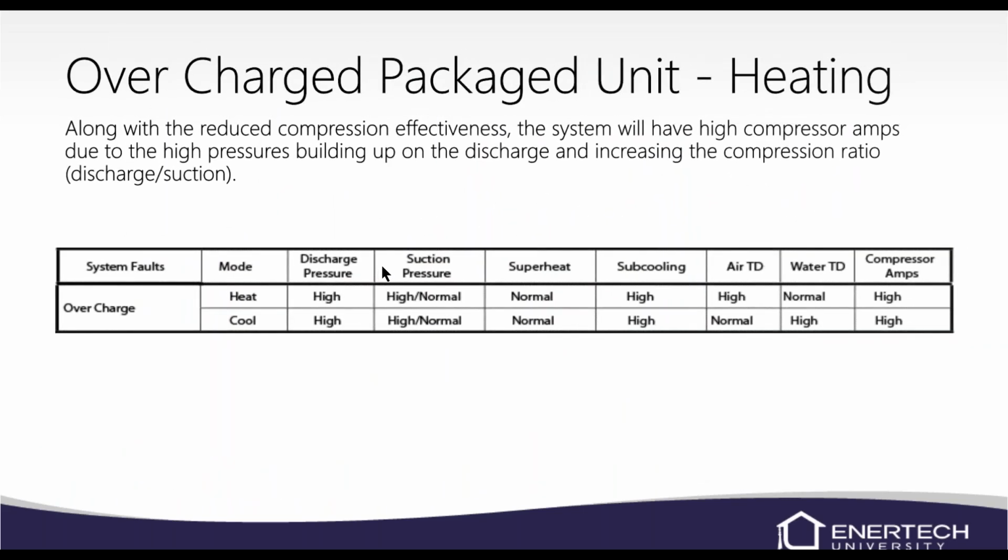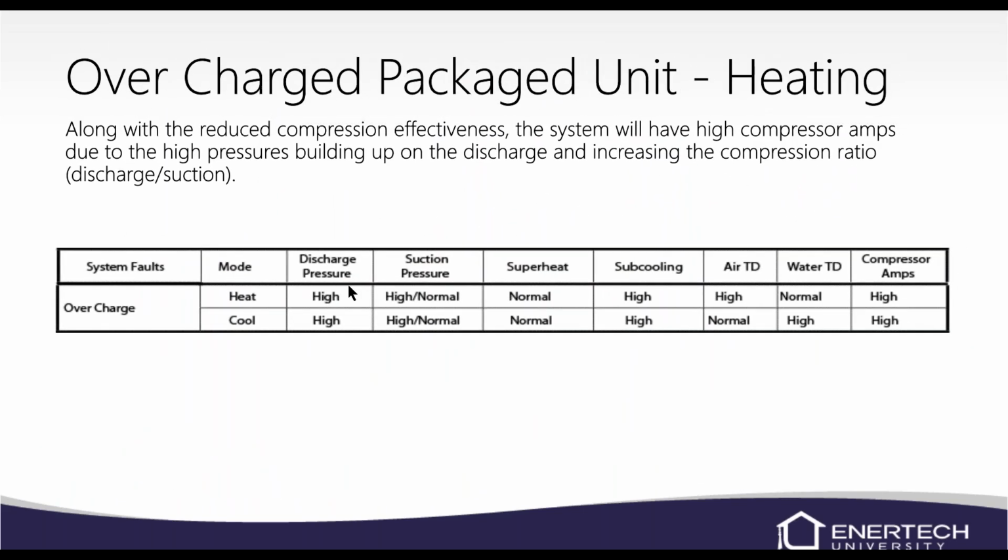Some of the symptoms of an overcharged system: high discharge pressure for sure. And a lot of times what it'll do is your suction will stay pretty consistent. It may raise a little bit, but your discharge will slowly start to rise. Sometimes it'll shoot up fairly quickly, and sometimes you can go out on high pressure. So again, your suction pressure could be normal, could be a little bit high. It won't be extremely high, but it'll be a little bit high.